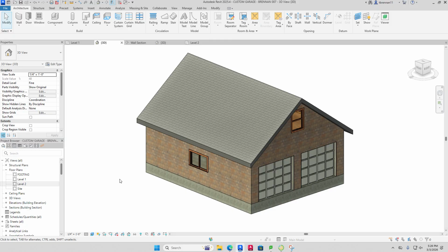I had to come up with a set of plans, which I did, and that was the first time I ever really knew what a wall section was. With a wall section, you're literally slicing through the wall to see what's in it. How does this wall go together? Now, why do we do this? Why is this something you have to do? The reason is this. Whenever you're dealing with a set of construction plans, you have to make it clear enough so that anybody who has a set of plans can't screw it up.